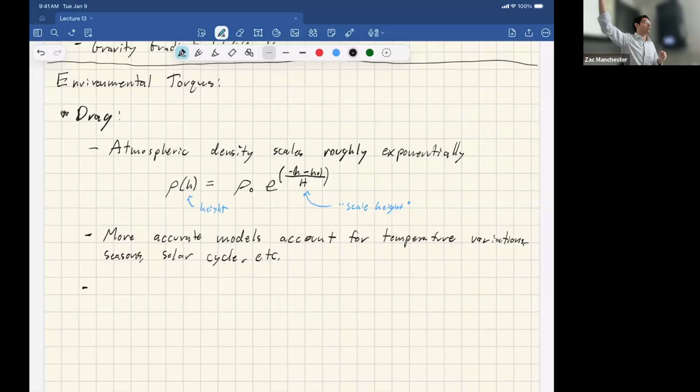So it tails off really quickly as a function of altitude. And interestingly, 600 kilometers is traditionally considered a vague cutoff for where you stop worrying about drag and start worrying about other effects. The gist is that when you're below about 600 kilometers, drag is the dominant perturbation. It dominates over everything else except two-body gravity effects. Once you get above 600 and this tails off, then other effects start to matter about as much. And that's considered the crossover point.